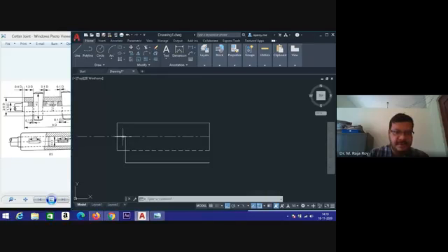After that, the same thing you have to get on the top side. The same part is there on the top side, so I have to get these two lines on the top side. For that I can use the mirror command. Go to this modify panel, and here this is the mirror command. Select the mirror command. Select these two lines. Then type enter to complete the select objects part.